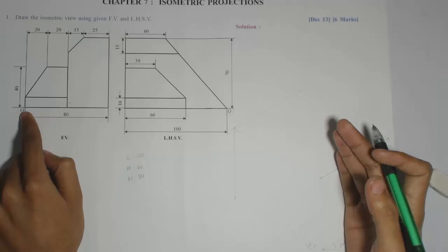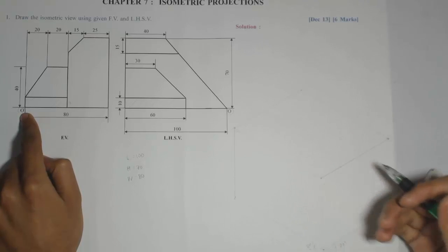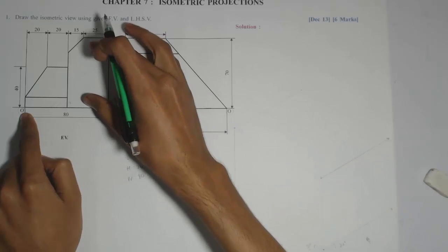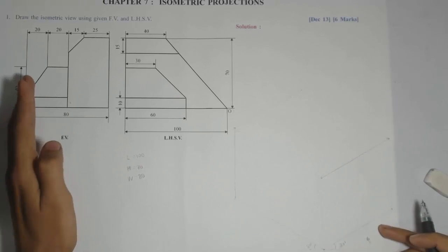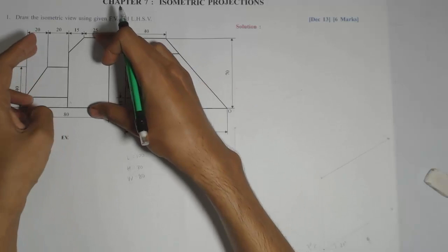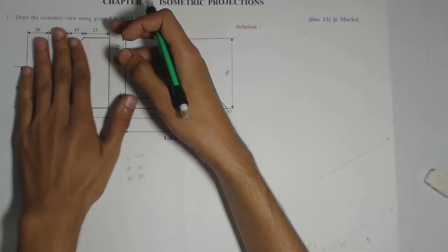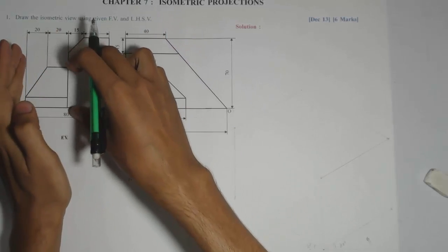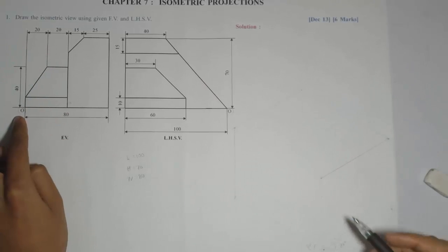The significance of origin is to decide the order in which we are going to get the front view. So you should not draw this view here. I should start from this end because the origin is here, so I'll go in this direction. This entire front view, which is now a flat surface, I need to tilt on a 30-degree inclined plane, keeping this O coinciding with this origin.